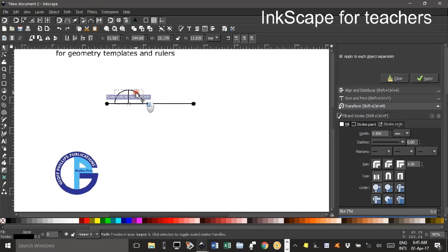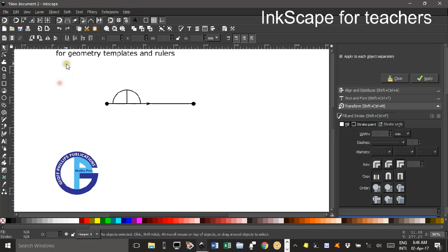I'm going to see if I can snap that on there. Sometimes you try to move things around and they try to snap back to other places. If you get it roughly right, you can always use the select tool again, second time, and left arrow to move across if you want it a bit closer. Or you could turn off all the snapping tools and just drag it easily without any snapping annoyances.